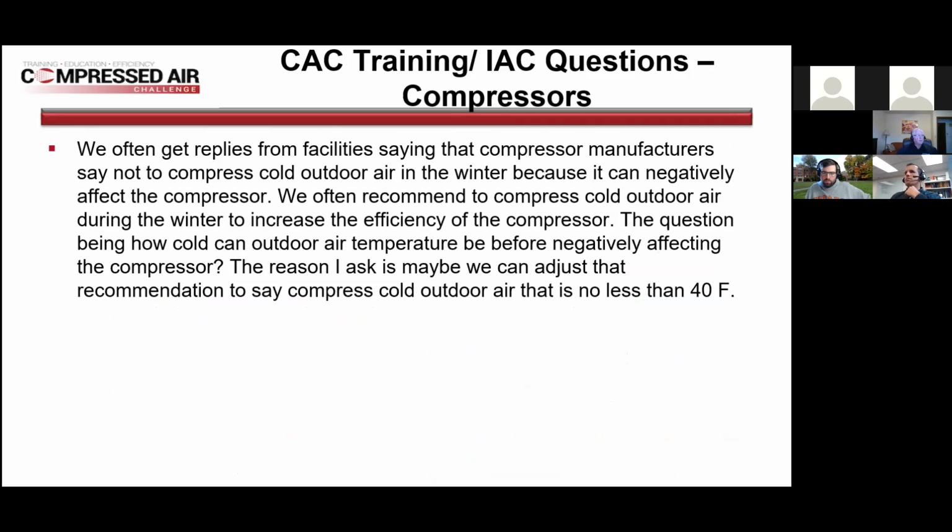So we often get replies that it's too cold, we can't go through and do it. How cold is too cold? And should it be adjusted to 40 degrees? Again, it depends on the type of compressor. The one that I've heard the most on is for the flooded screws. The concern there is if you have it shut off and it constantly has outside air going into it, the oil will get too cold and it'll be too hard to start up.